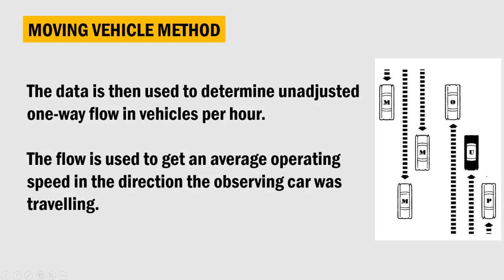It is an economical method of conducting a speed study, as it only requires one individual driving and the other counting. The need for two individuals can be eliminated by fitting a dash cam on a vehicle and replaying the video afterwards to count the vehicles.